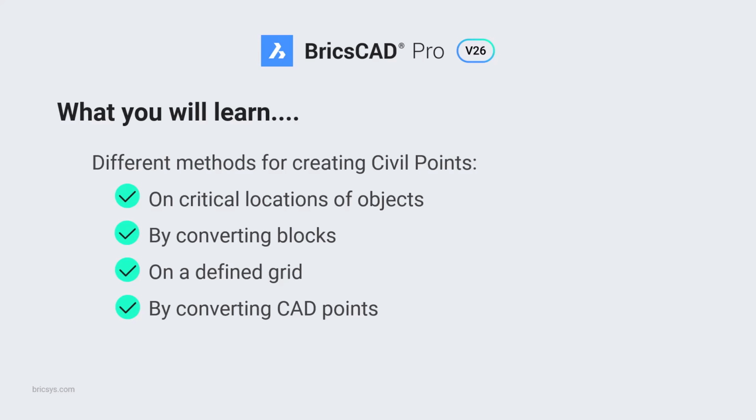BricsCAD gives you different ways to create civil points, depending on what your project calls for. You can place them right at the critical locations of objects, convert existing blocks, generate them on a defined grid, or even just convert plain CAD points. No matter how your design is set up, there is a fast and reliable way to turn it into civil points. And in a minute, I'll show you exactly how easy it is.